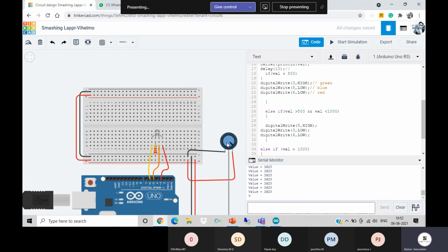And with this as well, whenever we have that soil moisture sensor, we will be using the value sent by the soil moisture sensor to control the pump system to automatically irrigate the soil. That is how a smart irrigation system works. We require a soil moisture sensor, a pump system with a relay, and a controller. When the moisture drops to a particular limit, we require the pump to be turned on.